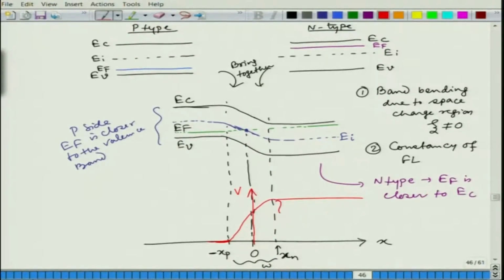Okay. So, due to the space charge region we are having this particular potential V naught, and in terms of the energy height, that is how much the band is bent, you can write it as charge into potential, that is the potential energy height. Okay. And the field is in between the space charge region, and we can write that it is a function of x.